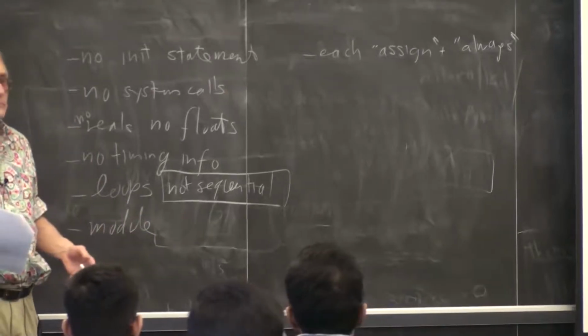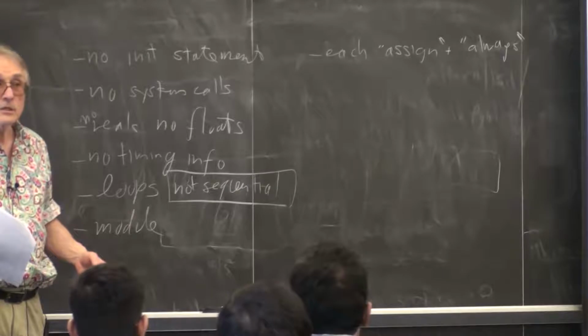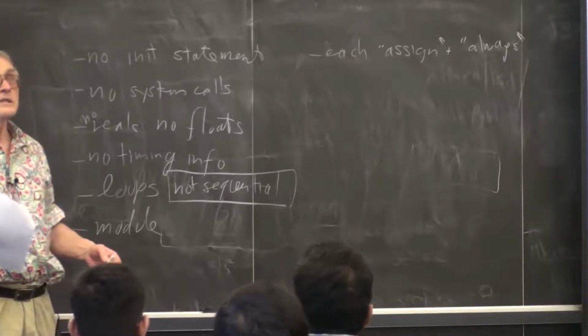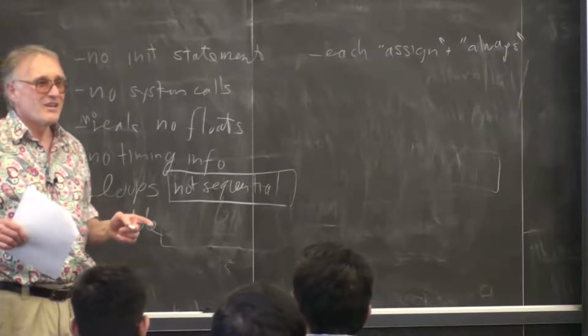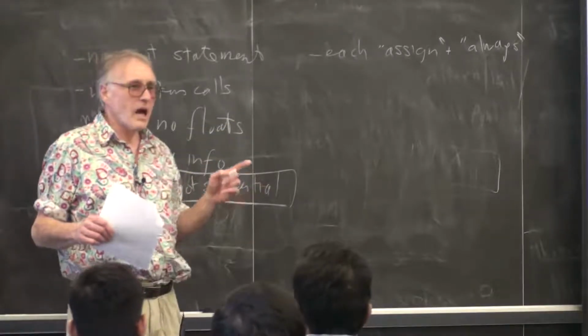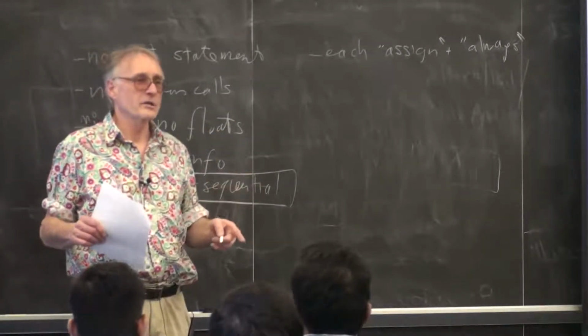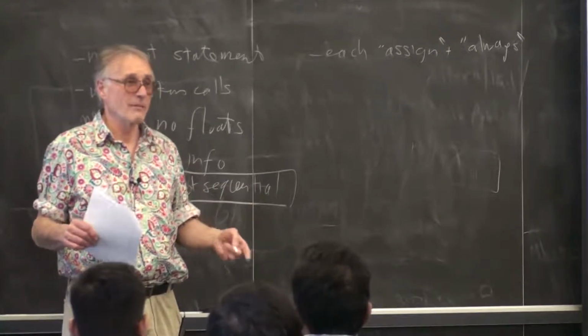Is negedge synthesizable on these chips? It is synthesizable, but you can't use both. You can't say always on pos edge or neg edge. You can say neg edge or pos edge, but not both.